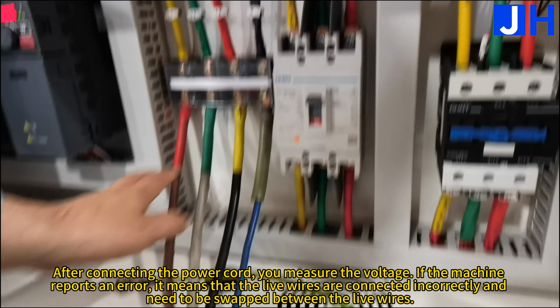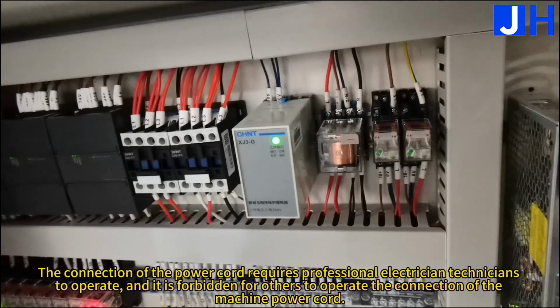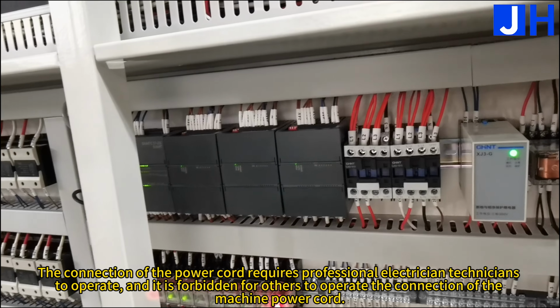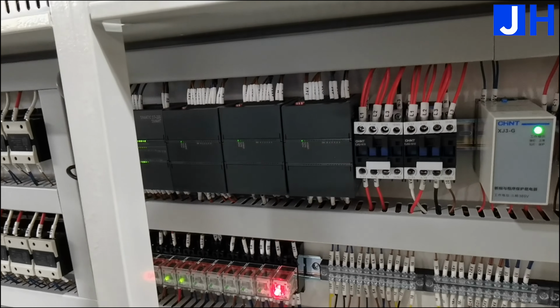between the live wires. If the live wire connection is correct, this shows a green light. The red light is displayed here. We need to turn off the power and switch between the live wires. The connection of the power cord requires professional electrician technicians to operate, and it is forbidden for others to operate the connection of the machine power cord.